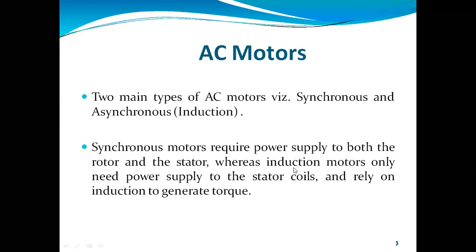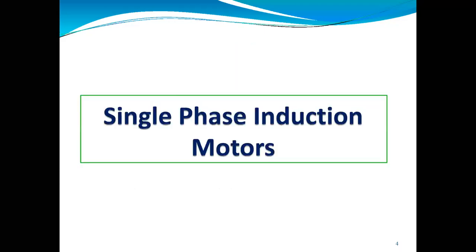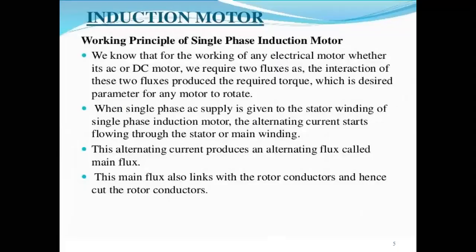That type of machine will not require power supply to both. It means the induction motor requires power supply only to the stator, and it depends on induction to generate the torque. Here the rotor will not require the power supply. So firstly we will see how we can make the asynchronous, that means induction, motor. There are two types, single phase and three phase induction motor. Firstly we will see the single phase induction motor.